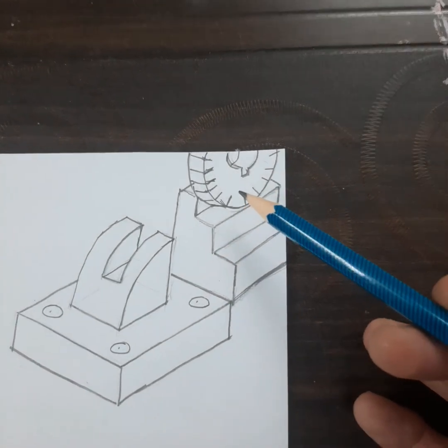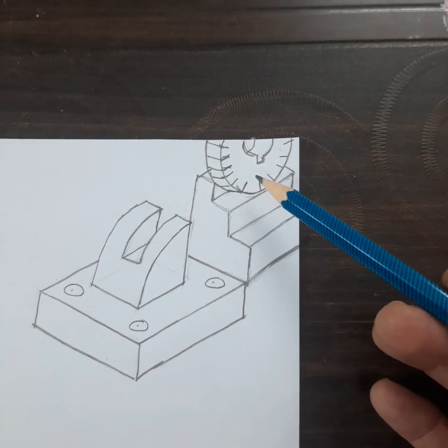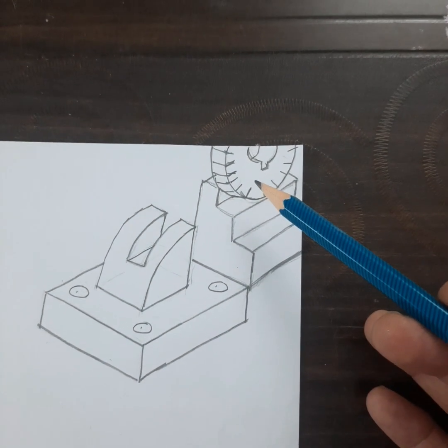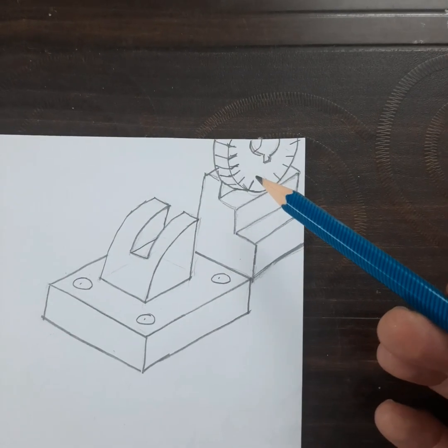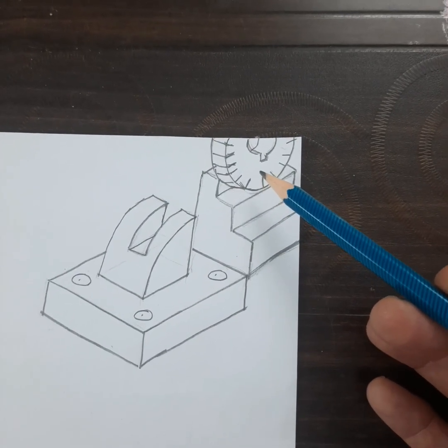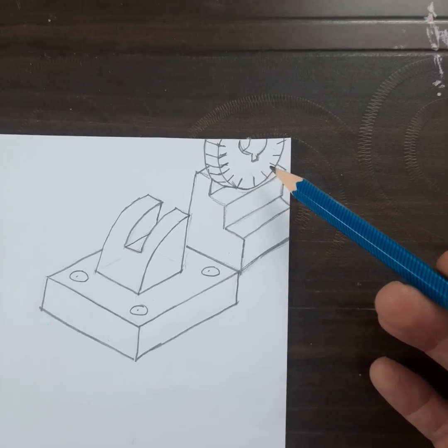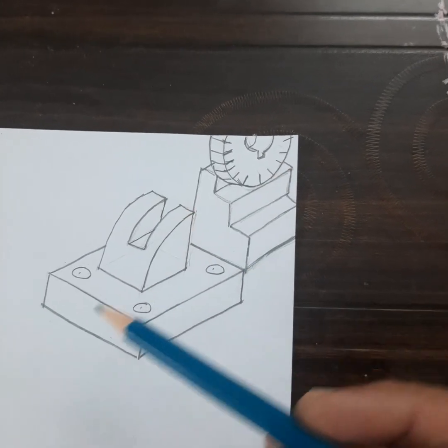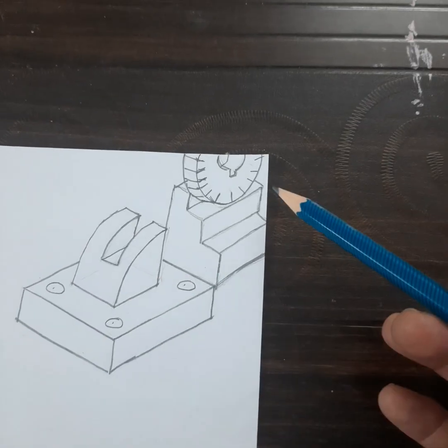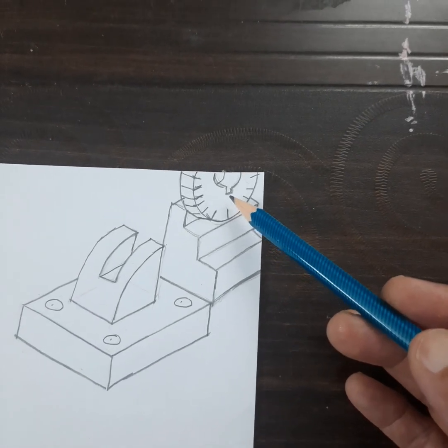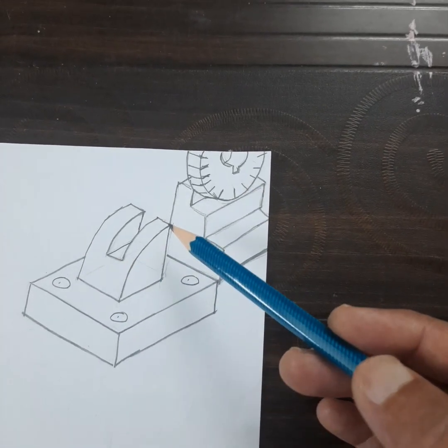The milling cutter is shown here. The type of milling cutter is side and face milling cutter. So we are going to use this on a horizontal milling machine, and the rotating milling cutter is used for milling the slot, and when the component is pushed against the rotating cutter, you get the slot machined on the workpiece.